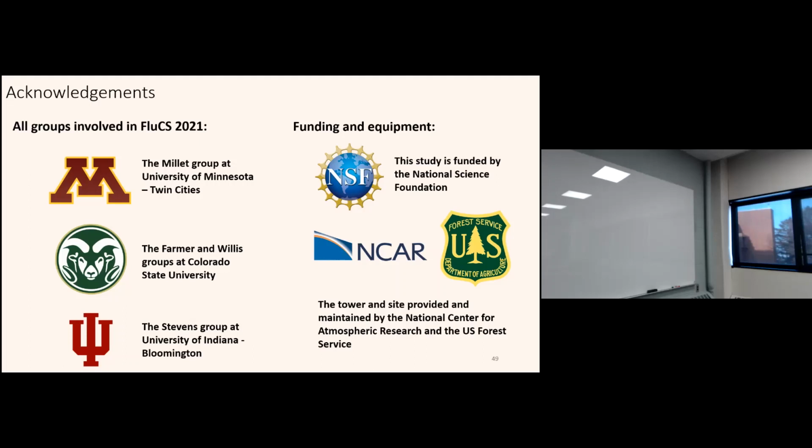But how do you measure the organics, I guess? So what we do is we measure the inorganic ammonium and nitrate, and then we do an autoclave persulfate digestion, and then we run the nitrogen again. We run the ammonium again on the sample, and by difference we assume that is organic. And it's quite a bit. We are seeing between 15 to 20 pounds per acre per year being deposited in that particular form.